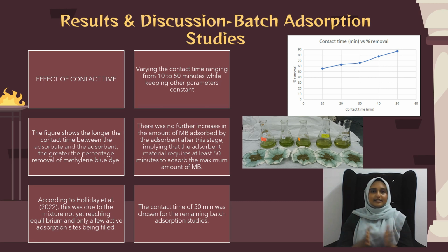So there was no further increase in the amount of methylene blue adsorbed by the adsorbent after this stage, implying that the adsorbent material requires at least 15 minutes to adsorb the maximum amount of methylene blue. According to Holiday et al. 2022, this was because the mixture had not yet reached equilibrium and only a few active adsorption sites were being filled. Therefore, the contact time of 15 minutes was chosen for the remaining batch adsorption studies.